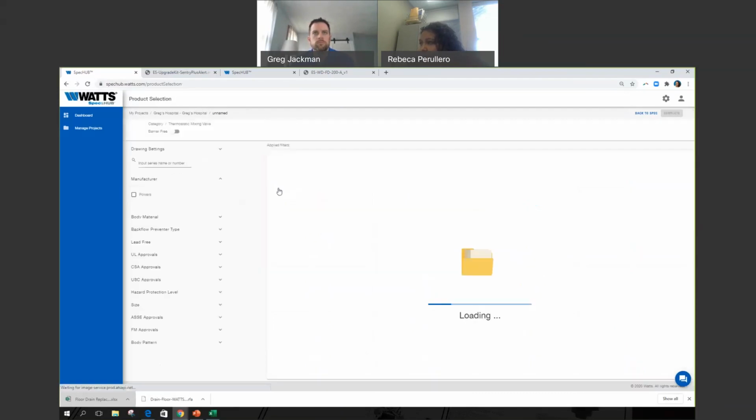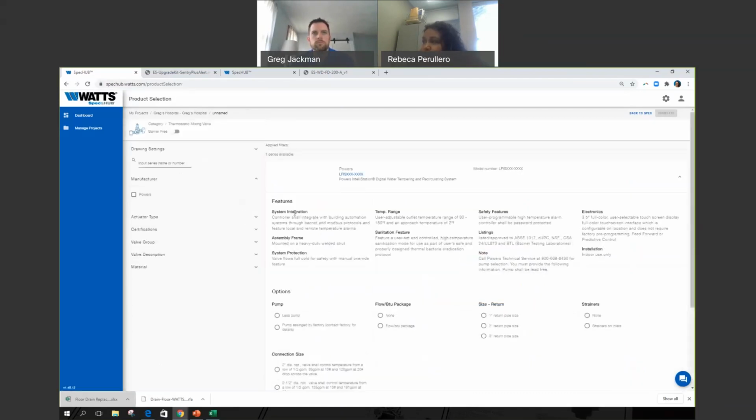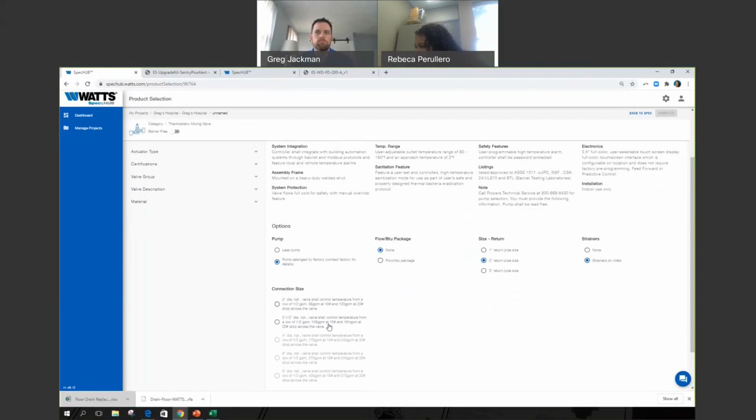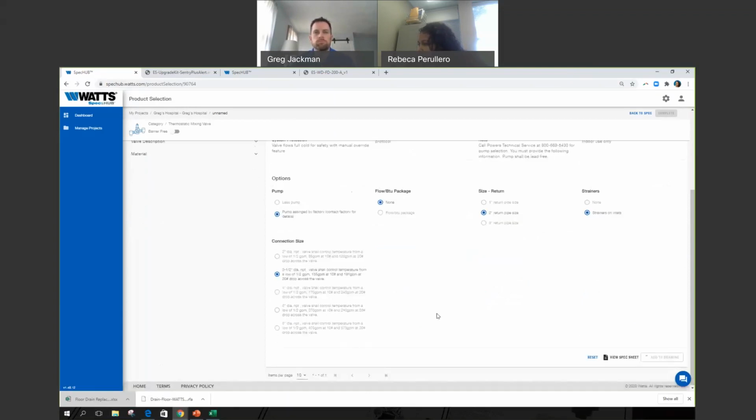I'm going to click that, and it'll take me directly to the page where I can configure my mixing valve. I'm going to choose it with a pump assembly. I know my flow and BTU package. Actually, no, I don't know it. I'll choose my pipe size, 2 inches. I would like strainers on the inlet. And I'm going to read it here: 191 GPM. All right, I'll go with that.